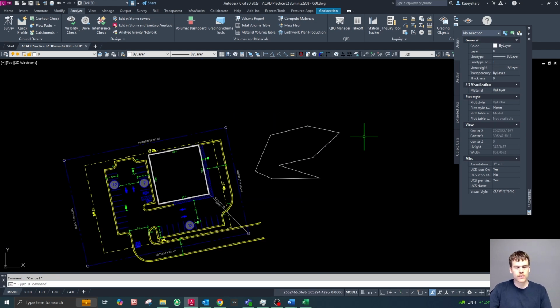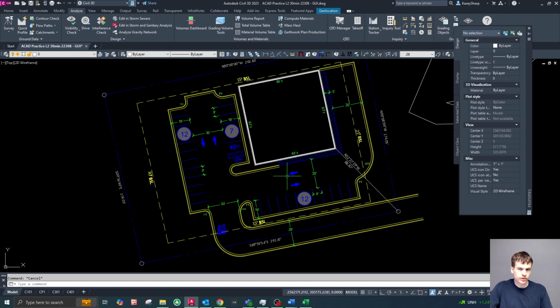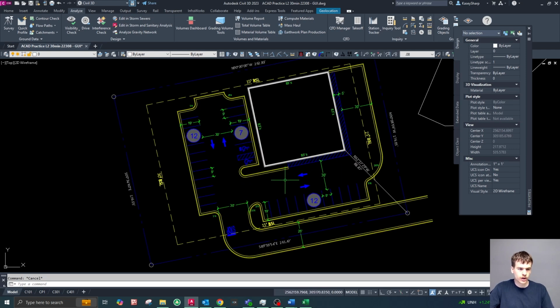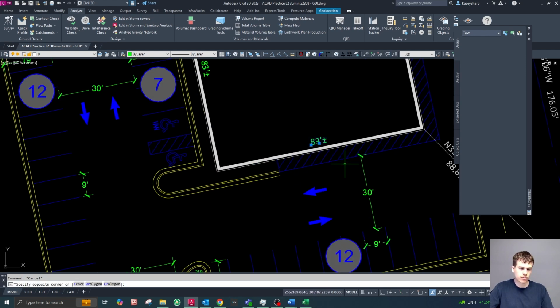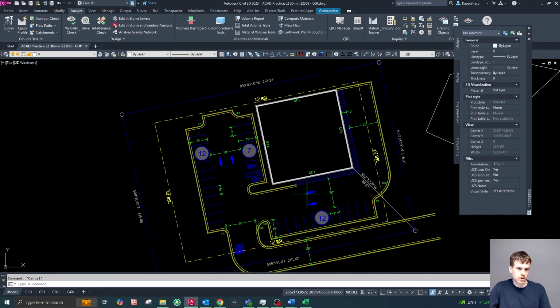Okay, and once you have a good grasp on all of these commands, line, polyline, offset, fillet, arc, you're going to essentially be able to draft pretty much any site that's thrown your way, right? You can navigate your drawing using just your mouse hand, select whatever piece of information that you want. Using all of our different middle mouse button commands, you can change your ortho, you could set your UCS to whatever you need it to be.